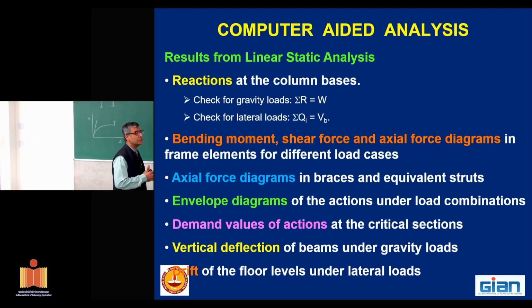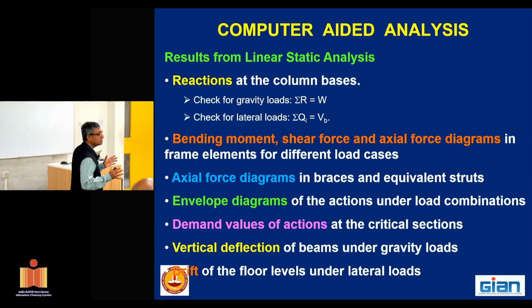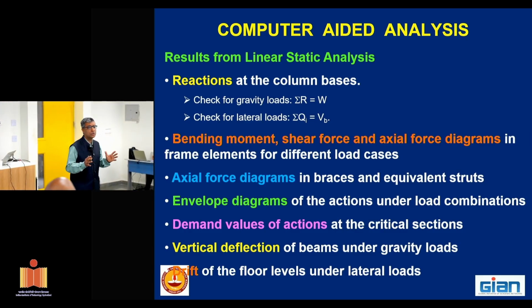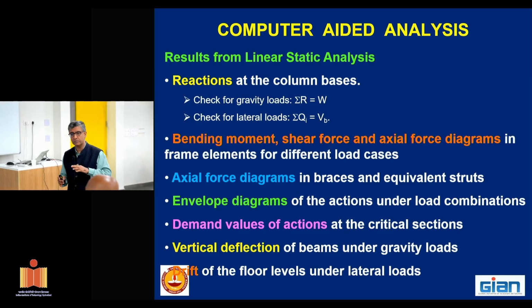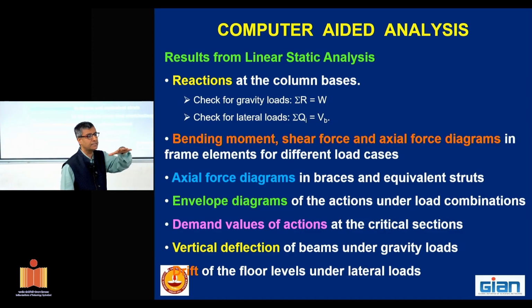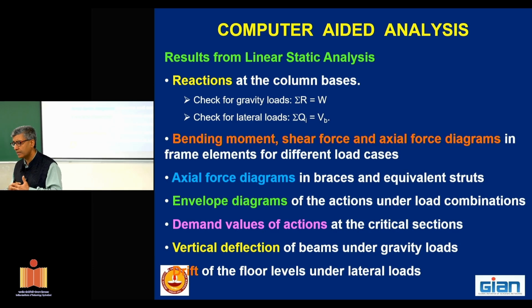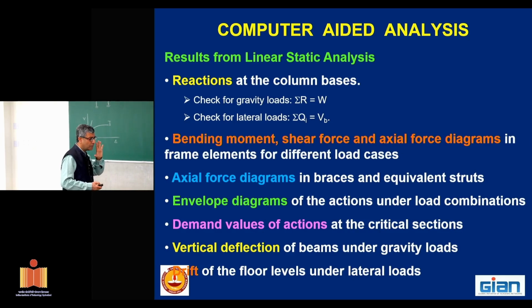Now from the analysis, first you have to do some checks. Once you're in a design office, there is no teacher to go through your calculations. You have to do your checks. Even as a research student, you cannot expect that your guide is there to correct your results. No way. You have to check. How do you check? You have to make sure that whatever reactions you are getting under the dead load are more or less close to the estimate of the weight of the building. You're already estimating the weight of the building while calculating the seismic force. Your analysis should also give that. Similarly, whatever lateral load you're applying and whatever reactions you're getting, the sum total should be equal to the base shear that you have calculated.